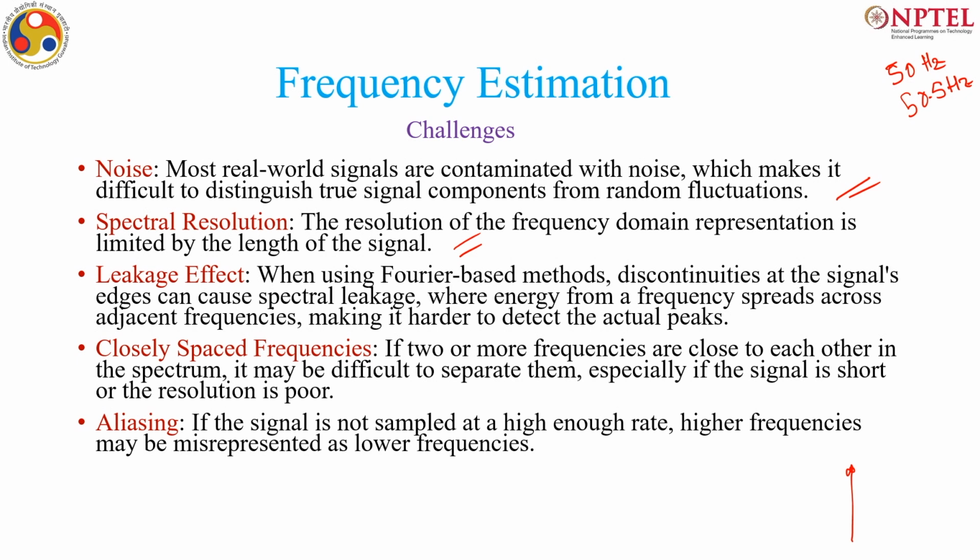That means multiplying that sine with a window function, and we know that because of this windowing, instead of getting a sharp peak you get a spread out peak, and probably this 50.5 will be spread out like this. So, this will sometimes appear as a single peak, and this is the same problem as closely spaced frequencies which I said.